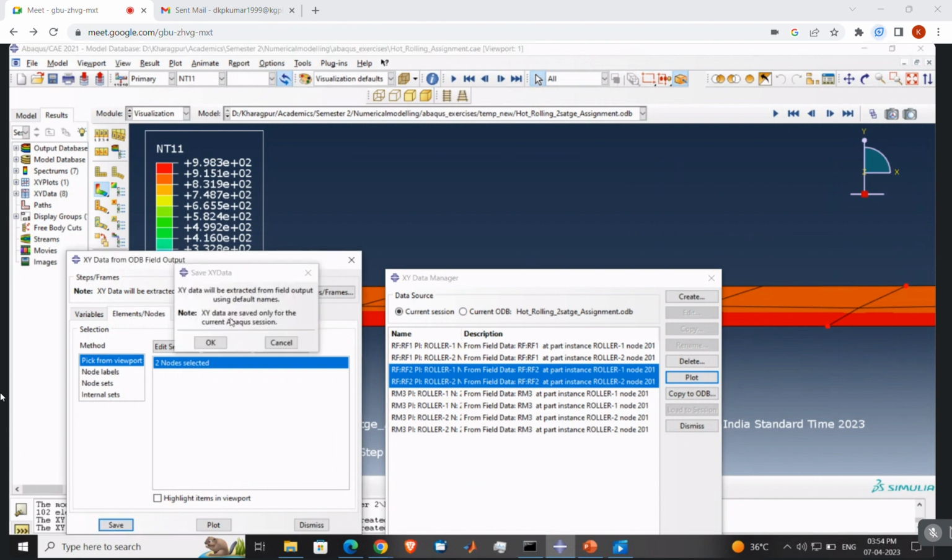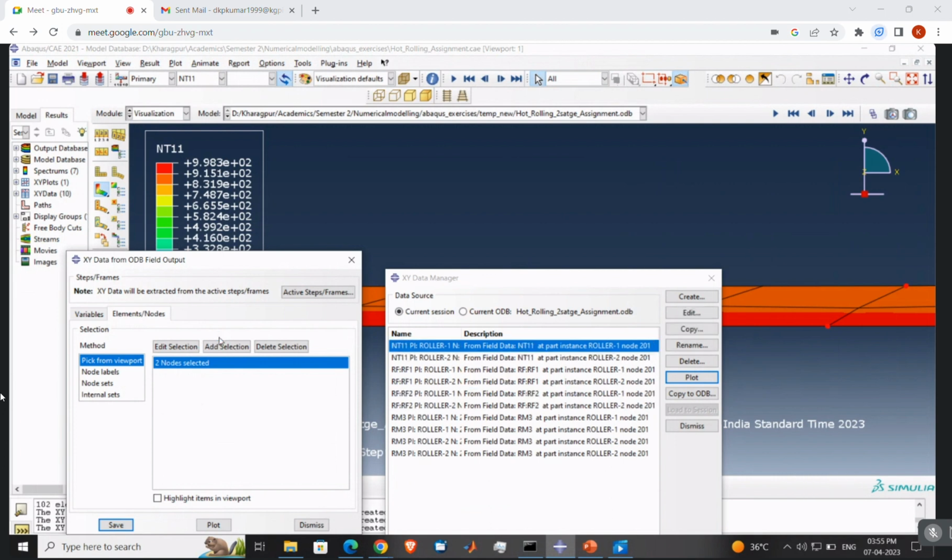That is how we take the temperatures on the stock. One is on the top surface, the other one is on the middle plane. By logic, the top surface is more in interaction with the outer surfaces, so there is a high temperature loss at the top surface when compared to the middle surface. The middle surface, because it is at a very high temperature, has the internal heat already present. It will be at the higher side of temperature for most of the operations.